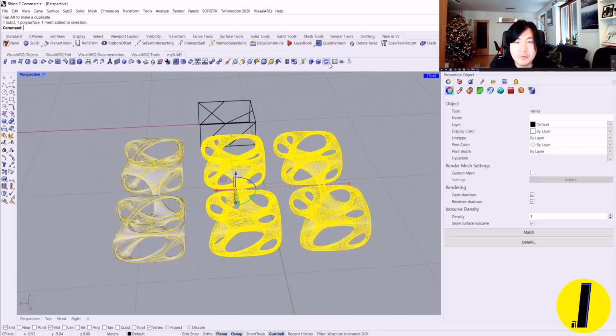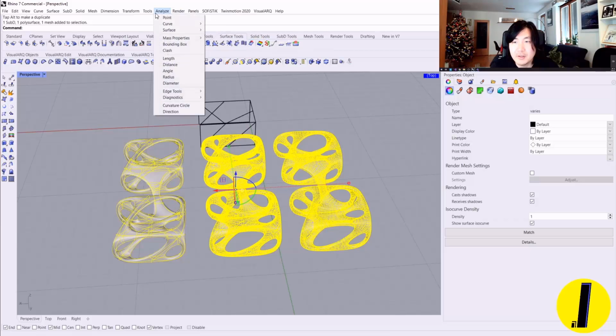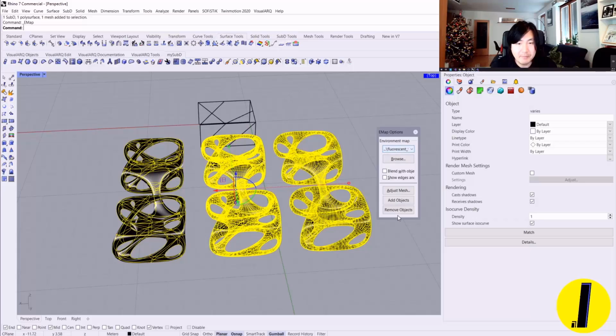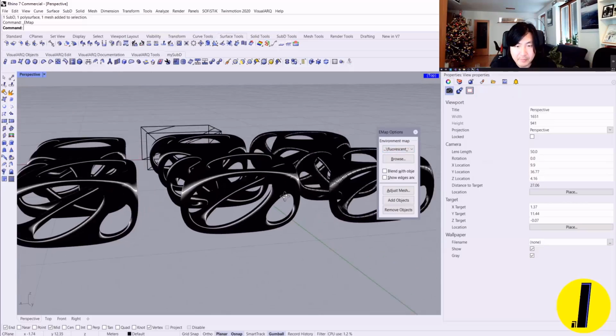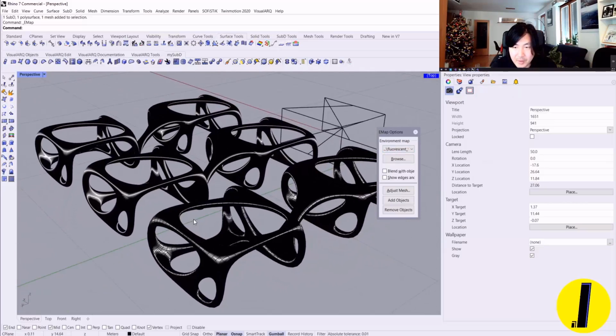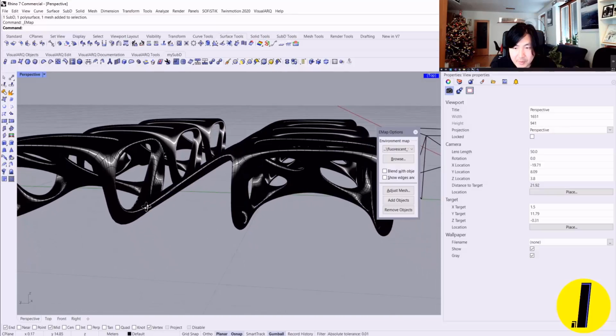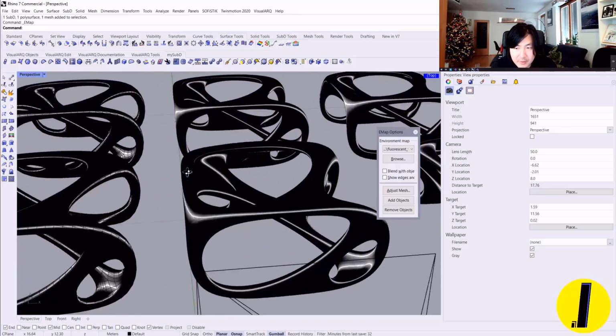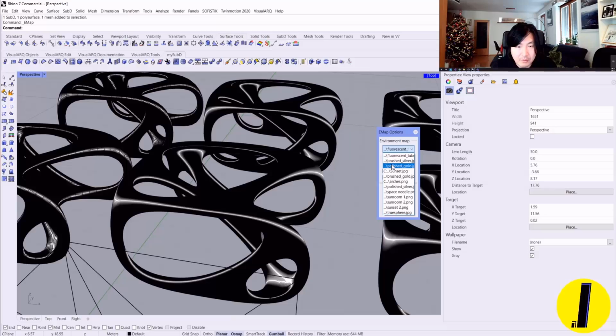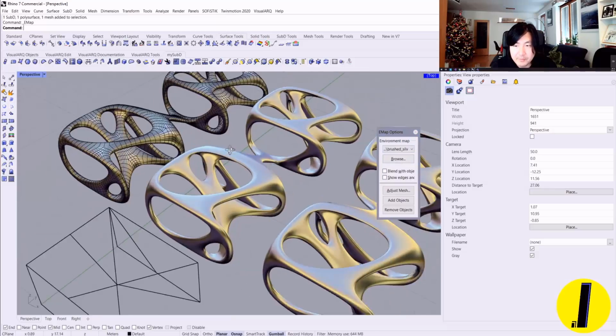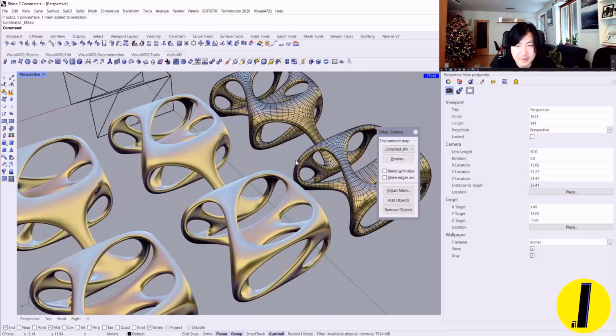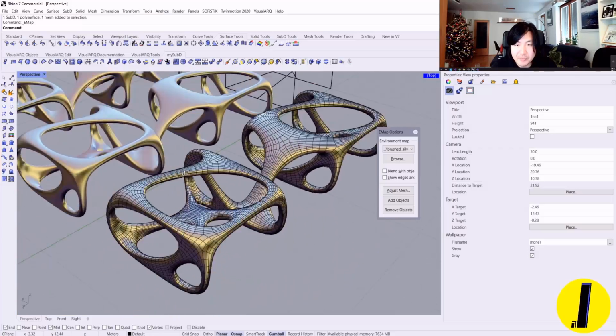So I'm going to click here, surface. Let's surface tool. I don't know where to find it. Okay, let's just go analyze surface, and I'm going to click on environmental map. And when I see them now, as you can see, they're keeping almost the same curvature. Let's make it brushed silver. Super nice, isn't it? Isn't it nice, really?